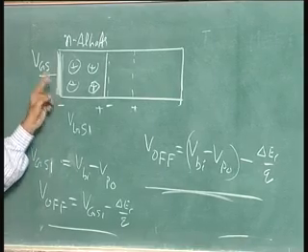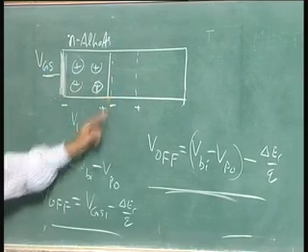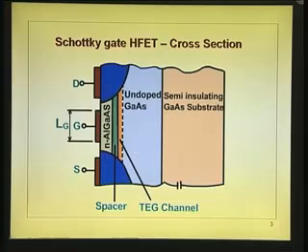So, when I change this voltage, negative charges will be brought in here, because there is a direct connection between the gate and these points. So, you are applying a voltage between the gate and the inversion layer in the case of MOSFET. Similarly, the additional voltage above the off voltage or threshold voltage, whatever you apply, will appear in this layer.